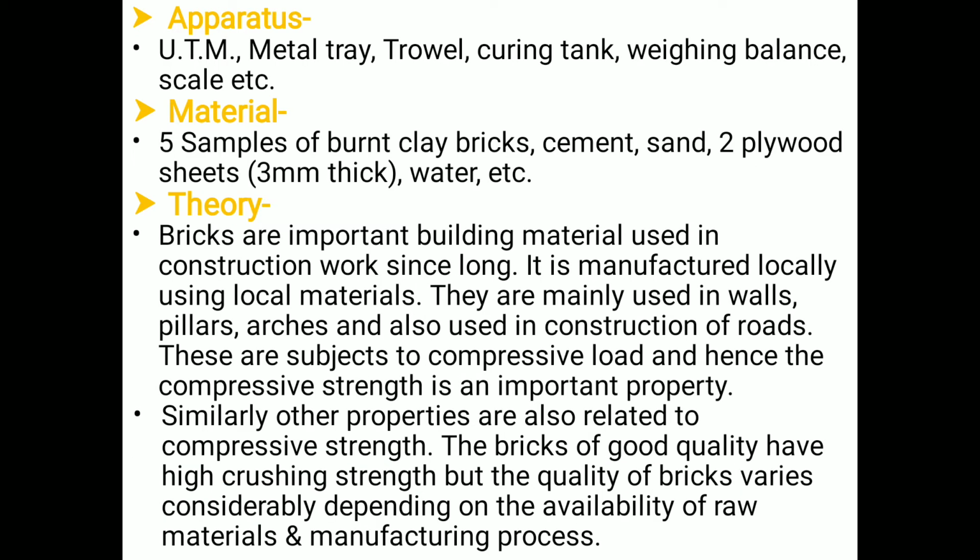The apparatus required is UTM. The full form of UTM is Universal Testing Machine. Next, we will require a metal tray, trowel, curing tank, weighing balance and scale. Those are the apparatus which we will require to perform the compression test of the brick.